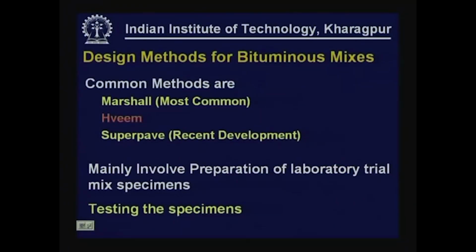As I indicated, there are various methods of designing bituminous mixes. A few common methods are Marshall method, this is the most commonly used method, film method, and Superpave mix design method. Superpave, as I indicated when we were discussing bituminous binders, refers to superior performing pavements. This is of a more recent development.